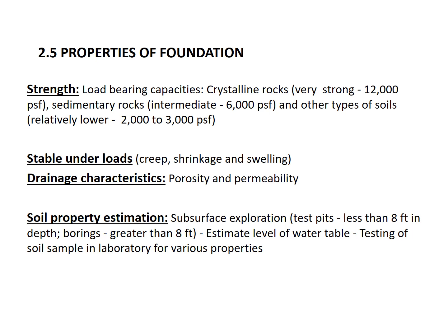So what are the properties of a foundation? Well, strength, the load-bearing capabilities. Now, crystalline rocks will support about 12,000 psf, and sedimentary rocks a little bit less, at 6,000 psf. And other types of soils are in the 2,000 to 3,000 range.